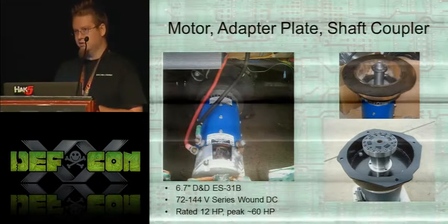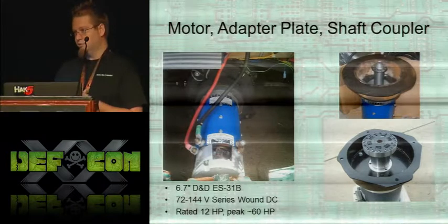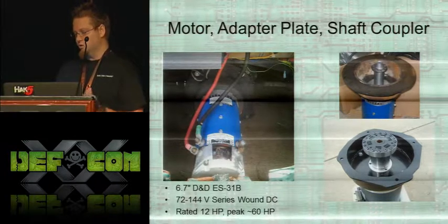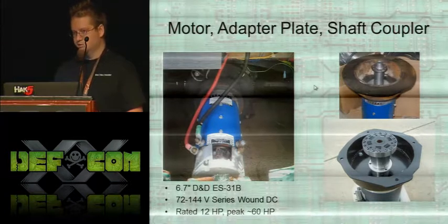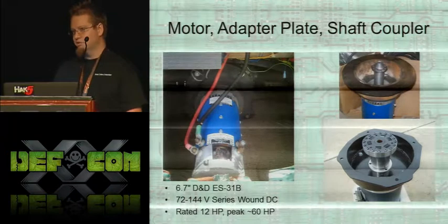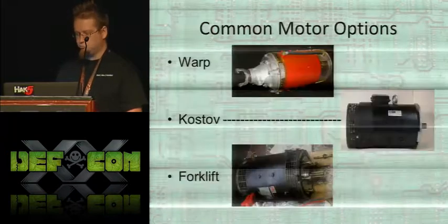It peaks at about 60 horsepower, running at 120 volts, and you can bump the voltage up if you want, and you can run more amps through it if you want also, if you blow some extra air through it to cool it off better. That's really the limit on the power that an electric motor has, is just the heating. You have to keep that under control.